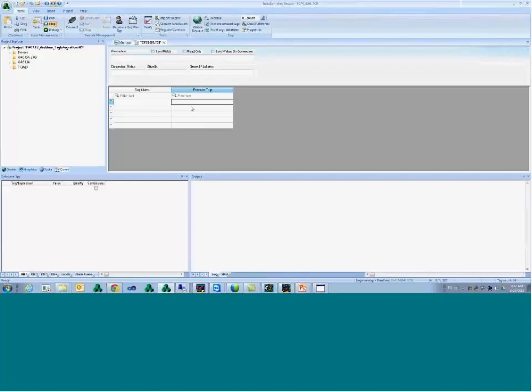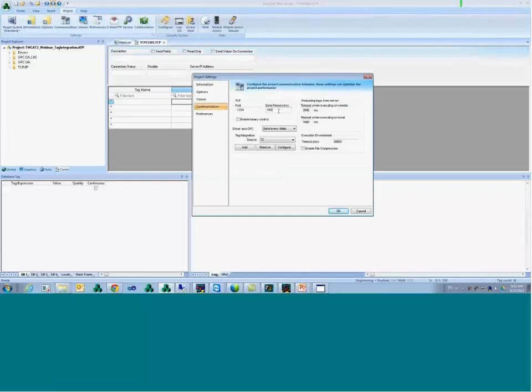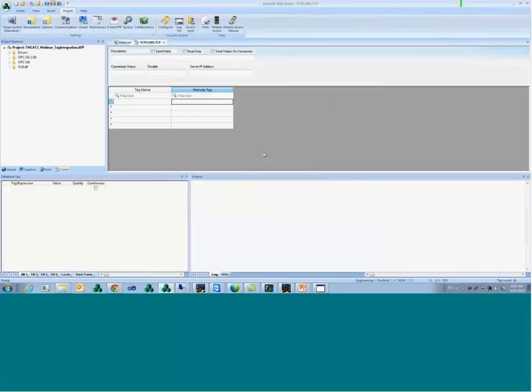This communication you can configure under communications, how often we're going to communicate. By default, 100 milliseconds. And you can change it to 10 milliseconds, which is the lowest you're going to get. So this is pretty fast. You may consider using that if you don't want to keep bombarding your PLC with messages. Let's say that you're going to have 10 web studios talking to the same PLC. That may be a little too much both on the network and on the PLC.